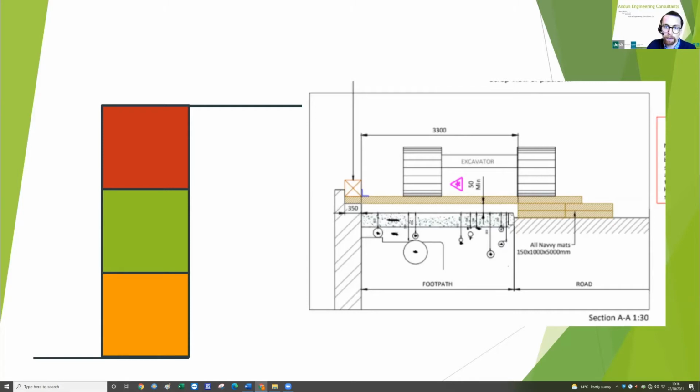That's kind of counterintuitive, bringing the crane or the load closer to the wall or on top of the wall to reduce the risk, but it's true, and it's something that we've employed on a number of occasions, just like this example here, where we avoided loading services in a footpath and also stabilized the retaining wall all in one swoop.